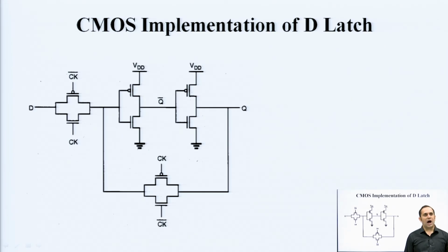How is it implemented? It is a very simple approach. You use what is known as a transmission gate. A transmission gate is nothing but a way of a multiplexing operation. You have a PMOS and you have an NMOS. Now, they both are complementary to each other. One triggers on high voltages, another triggers on low voltages.